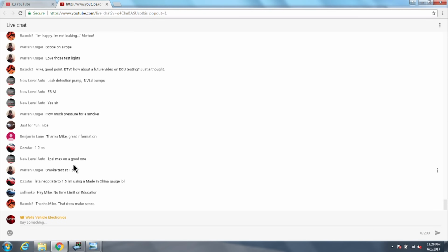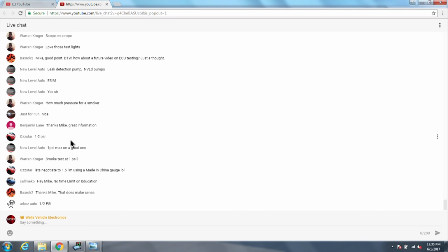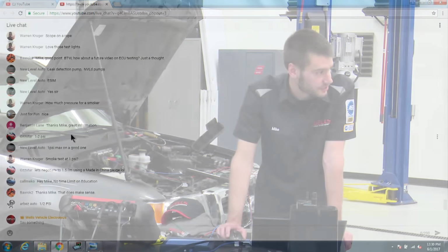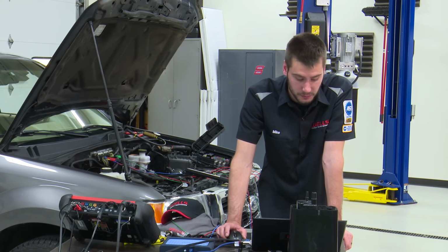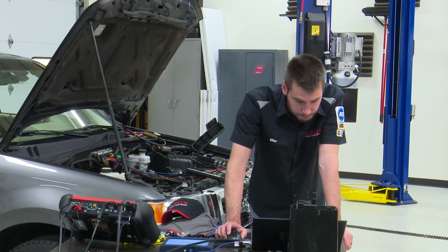So, yeah, 1 PSI max on a good one. You don't want to be overpressurizing the system. And like you guys saw, and like Eric O commented, when that vent solenoid was actually stuck closed, it was because the system was overpressurized at that point.